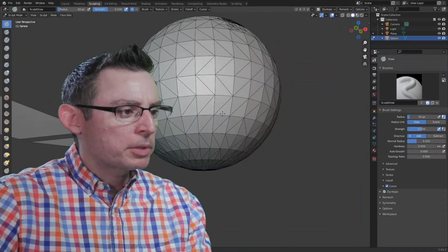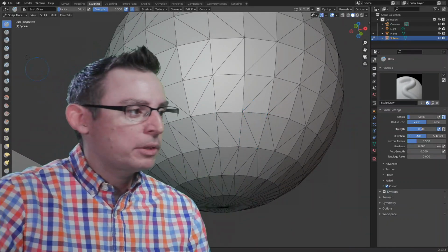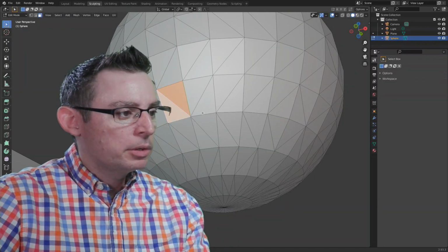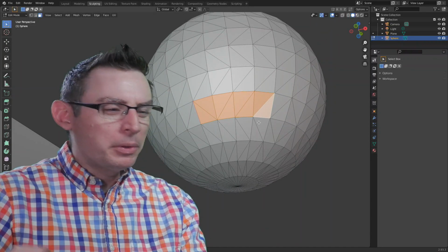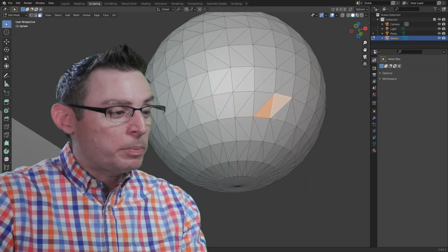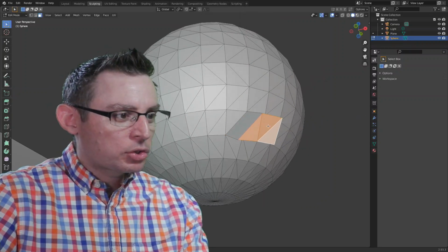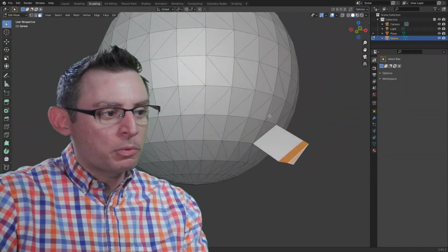And let's look at the bottom just to get away from the smaller triangles. So now, down here at the bottom, we don't have the luxury of that wonderful loop selection mode. See how I can't select those wonderful regions? I had to do it by hand. My ability to edit and make big sweeping changes when working with triangles is really quite reduced. If I was to extrude this now, we're getting a very different result than we were before.